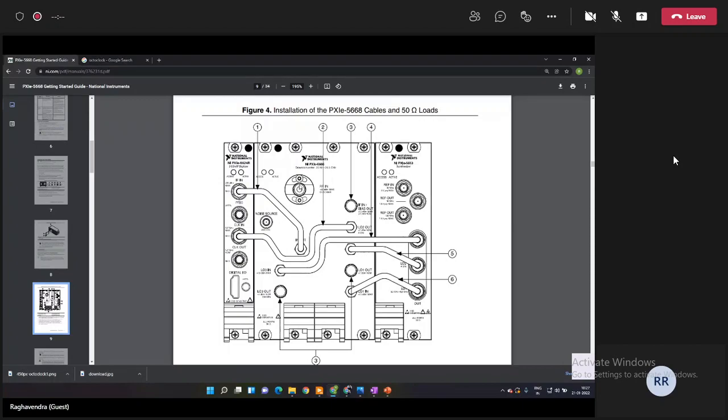But when you want to do 5G research, at least on the receiver end, you will be very limited when you choose USRPs, because just like the transmitters, the receivers are not capable of going beyond 6 gigahertz. To get around this, NI makes receivers. Again, there is no NI RF hardware that goes beyond 7.2, but there are receivers that go up to 26.5 gigahertz.